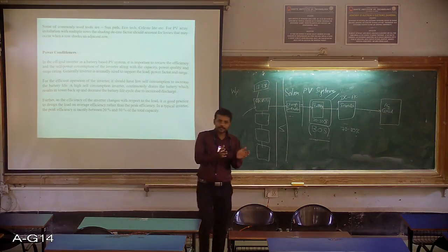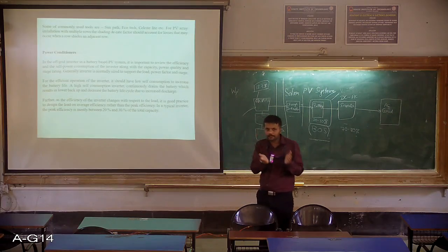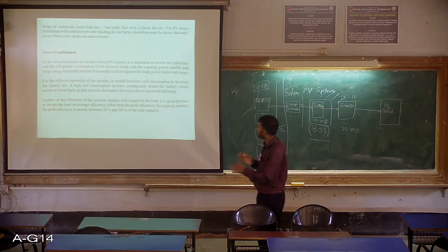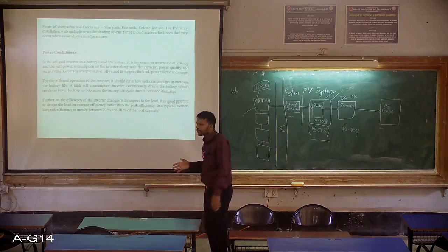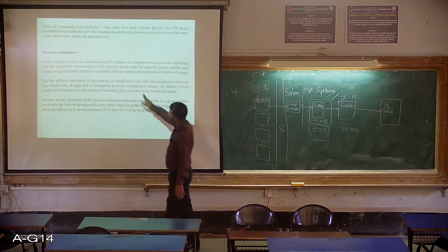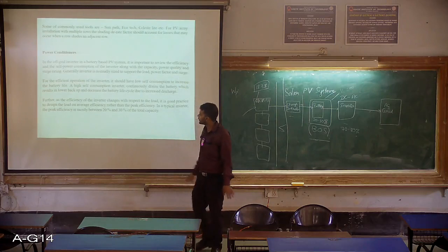The power conditioning unit we have already discussed. It has the inverter, MPPT and the charge controller. That entire setup we call the power conditioner. The main component in that is the inverter, and to select the size of the inverter we should consider the load, power factor and the surge.